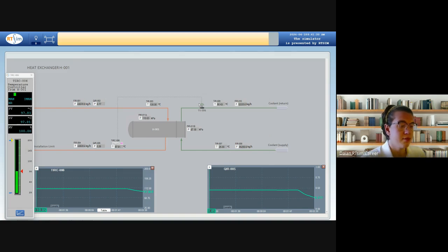And now we see the fraction of raw material, the complete increase of the amount of coolant. That is now the maximum amount of coolant is supplied, and the control valve is open for 100%. The cooling agent consumption is maximum.